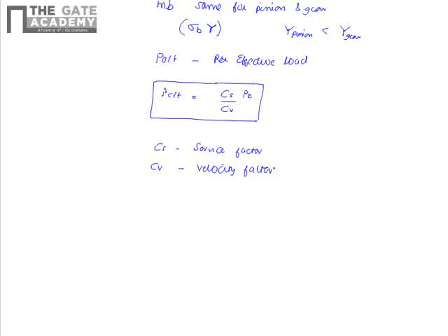We use a service factor because generally when we have a power transmission from one shaft to another shaft, the torque developed by the source of power varies during the work cycle. Therefore, the torque required by the driven machine also varies, and this is balanced by means of a flywheel. But in gear design, the maximum force is the criterion.